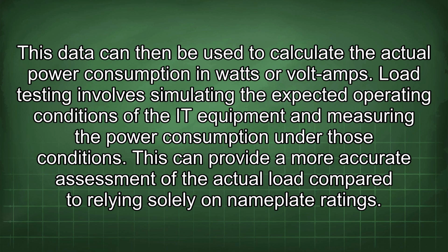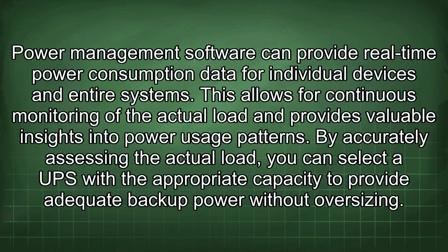Load testing involves simulating the expected operating conditions of the IT equipment and measuring the power consumption under those conditions. This can provide a more accurate assessment of the actual load compared to relying solely on nameplate ratings. Power management software can provide real-time power consumption data for individual devices and entire systems. This allows for continuous monitoring of the actual load and provides valuable insights into power usage patterns.